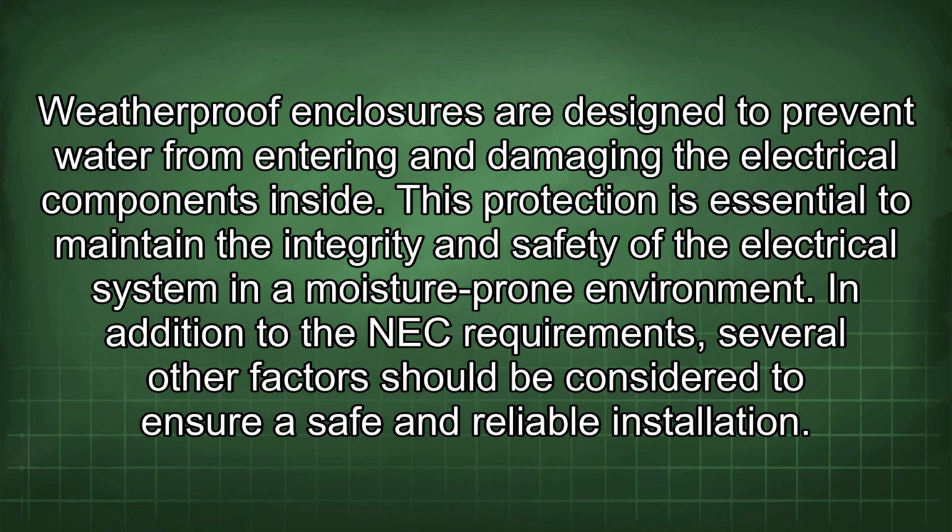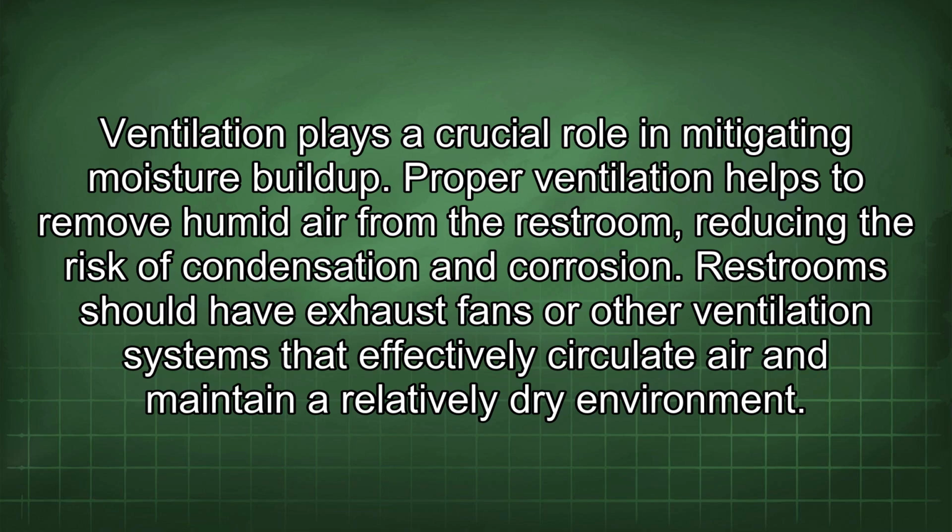In addition to the NEC requirements, several other factors should be considered to ensure a safe and reliable installation. Ventilation plays a crucial role in mitigating moisture buildup. Proper ventilation helps to remove humid air from the restroom, reducing the risk of condensation and corrosion. Restrooms should have exhaust fans or other ventilation systems that effectively circulate air and maintain a relatively dry environment.